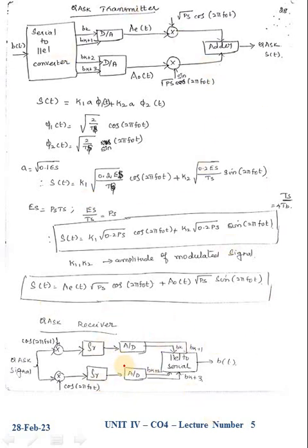In the receiver we need to demodulate the original signal, or recover the bit streams. It is similar to PSK. The QASK signal is applied to a product multiplier along with the high frequency carrier signal. Here we are using an integrator circuit.